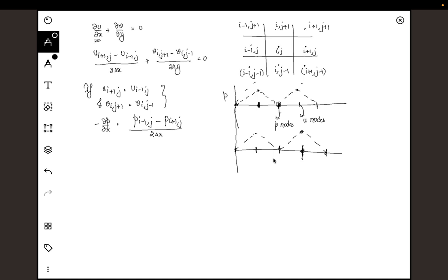So for example, if I have to calculate del u del x on this grid, let's say this is my u, and it is following the same pattern as pressure. If I calculate del u del x at this particular point, let's say this is my ith cell, this will be i plus half, this will be i minus half. So what would be my equation for gradient here?